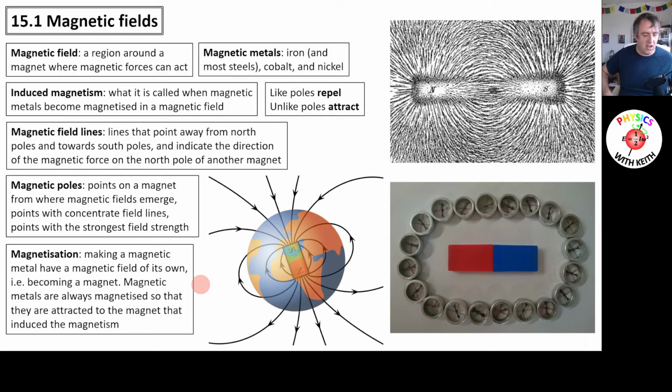Whereas in a magnetic hard drive, the magnetic disk in a hard drive, I don't know whether anyone still uses them anymore. Solid state drives have become the norm, but you could probably still get old magnetic storage. Those who want to use something which is magnetically softer so that you can change the direction of the magnetic poles on the small elements within the disk to set the bit to be 1 or 0. You don't want it to be too soft a magnet though, because otherwise, as soon as you've set that bit, the magnetic write head moves away from the disc, and then the bit flips all over the place anyway. So you want it not too hard, not too soft as a magnetic material.